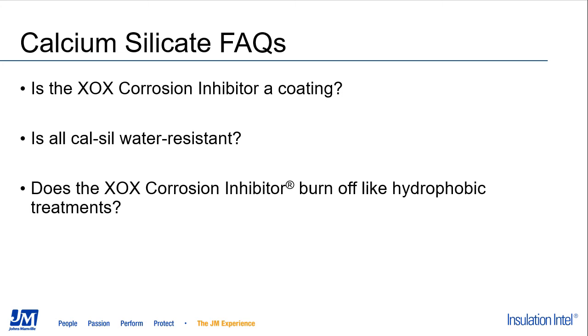And does the XOX corrosion inhibitor burn off like hydrophobic treatments can? And the answer to that is no. This is not something that is organic in nature and is going to burn off based on any operating temperatures that the material might be exposed to.